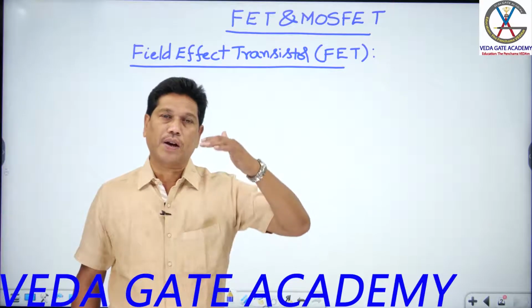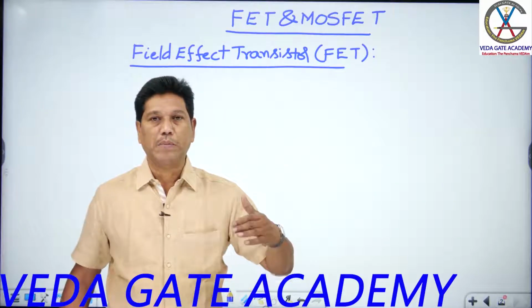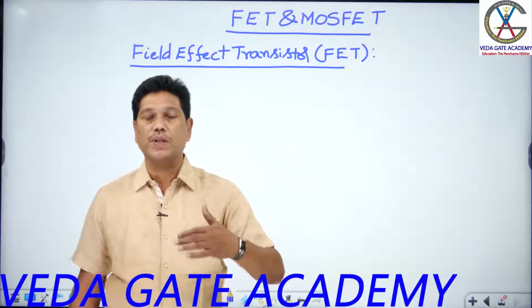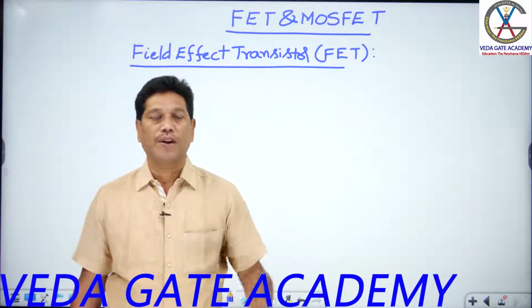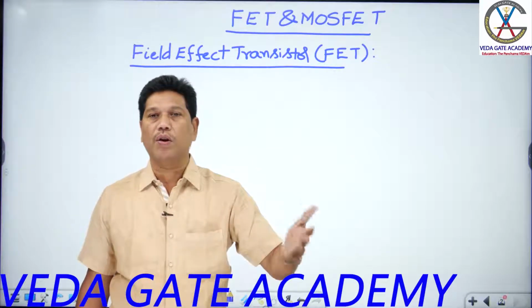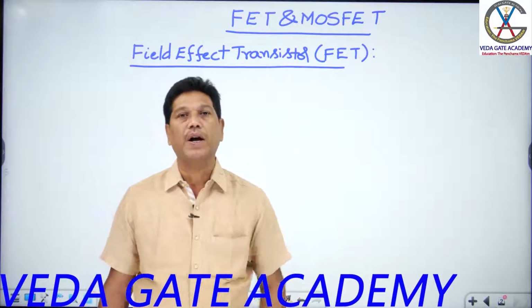Whenever the noise voltage crosses the limit specified by the noise margin, the output can have random changes irrespective of the input condition. So you find random changes at the output whenever the noise voltage crosses the limit specified by the noise margin.